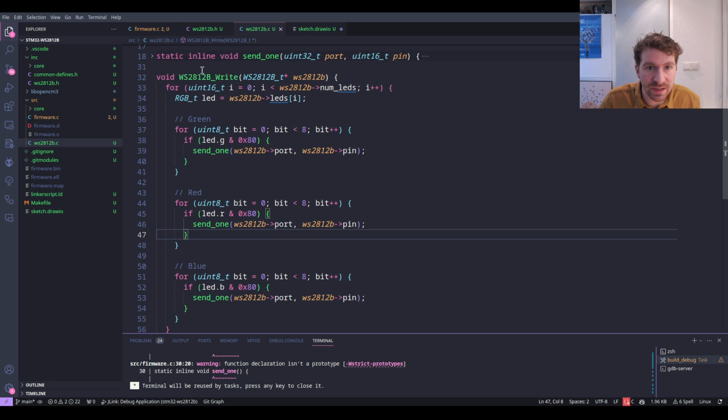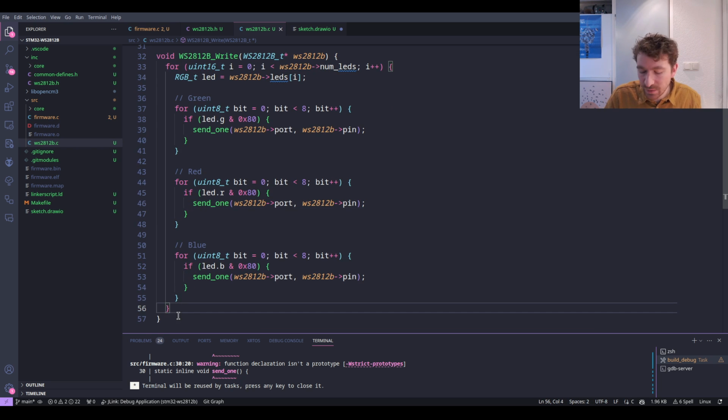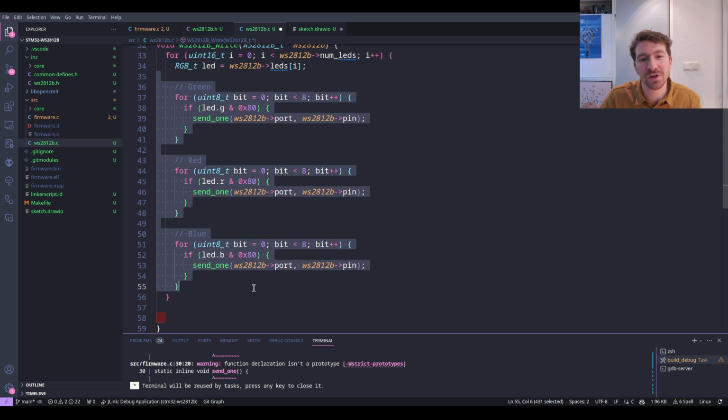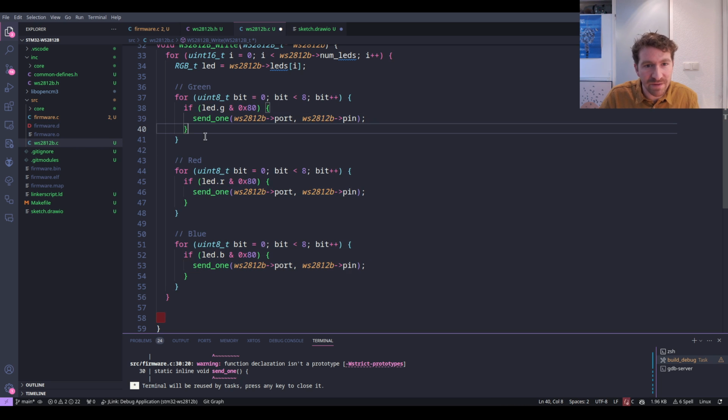Okay, so that is going to send that data, and then finally we need to wait 50 microseconds. We need to actually count 50 microseconds. This time I'm not going to insert the number of no-op instructions we need to get to 50,000 nanoseconds, because that's going to be a few too many for my liking. This is already quite a big function. Oh, we should have send zeros in all of these as well.